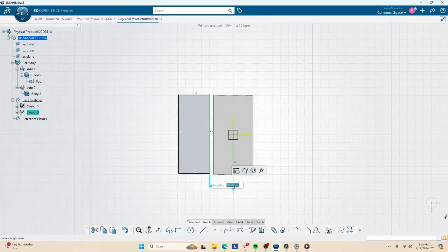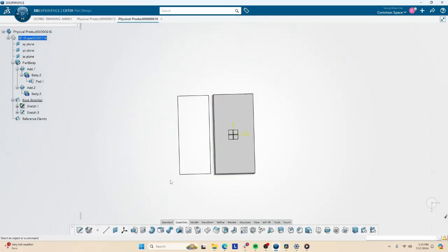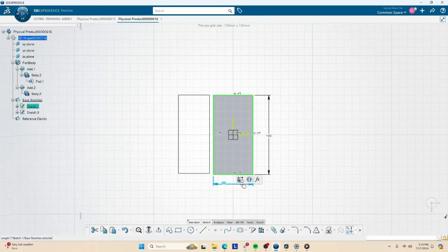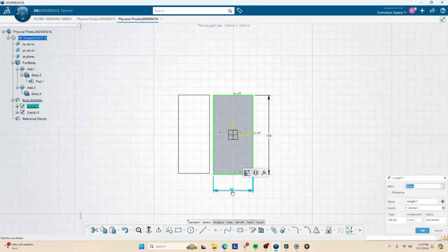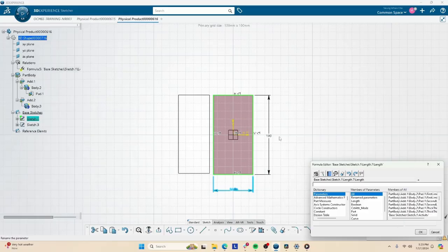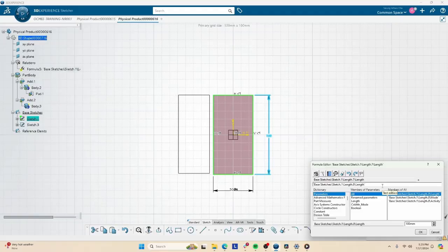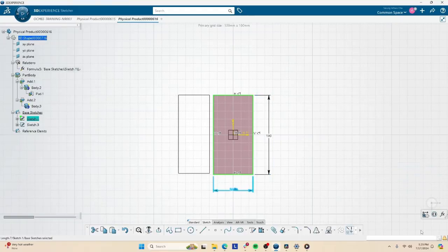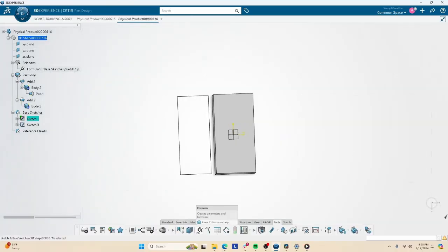Okay, for example, let's say I'm just going to leave that as the whatever value right now. I'll come back to it. Let's say go back to sketch 1, and let's say I want this to be always half of this value, and I'm sorry, it sort of changed before because I was playing around with the values. I could go, let me exit. I can go back into this, make it be a formula, and I could actually click this right into my little formula here, and I could use just your typical math operators to be half of whatever that value is, right?